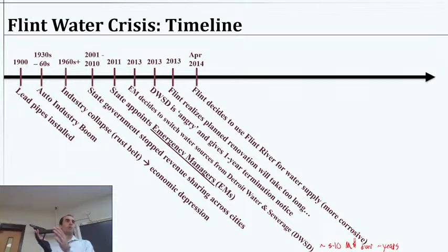And normally what we will do is operate in a way where we want the opposite of corrosion to happen. So rather than letting a pipe corrode until it breaks and water gets in from outside, or water's leaking out, rather than have that problem, we would rather have the problem, because it kind of goes in one direction or the other, where minerals slowly are depositing. Now, we don't want fast, huge mineral deposits to constrict our pipes like in a decade.